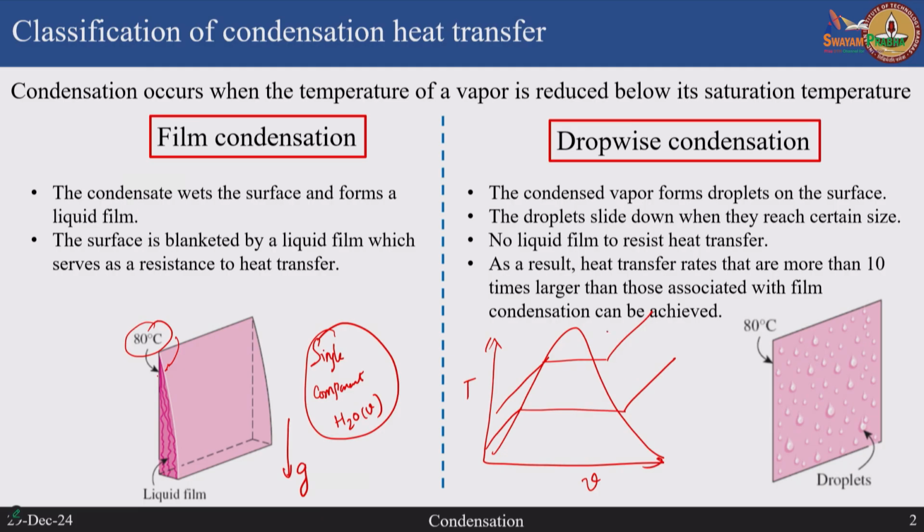This is for different increasing pressures. So, for example, in this case this is at 100 degrees, 1 atmosphere. If your surface temperature is 80 degrees, obviously the state of water has to be liquid. Therefore, it will now condense, and then the condensate will get accumulated.